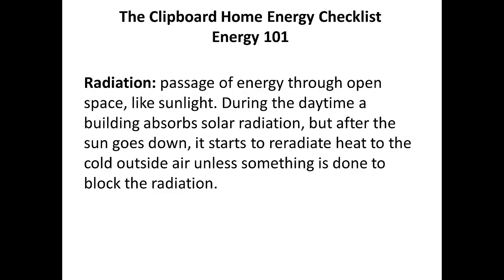And if you're sitting in a metal chair right now, and that metal chair has wood on it and metal, and you take your hand and touch that metal, it feels cold. It feels cool. But then you move your hand and touch a piece of wood, and it doesn't feel nearly as cold. Well, those two surfaces are exactly the same temperature.